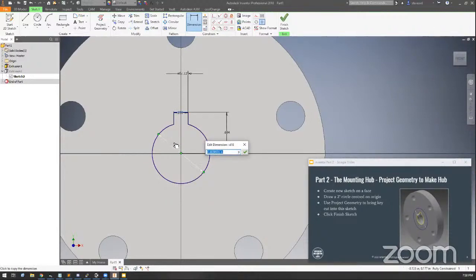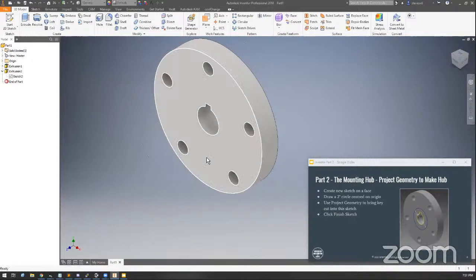Okay, so instead, what I'm going to do here is I can fix this by saying, okay, the edge of that circle I know is 1.5 inches. But what I want to do is I want half of the square to protrude above the perimeter of that circle. So I can take the height of that square and make it the center of that, and there that is. Okay, so now I've got this thing actually positioned and cut correctly.